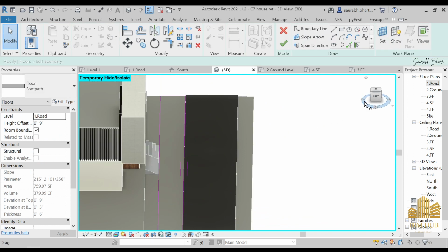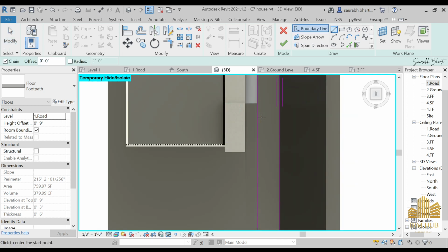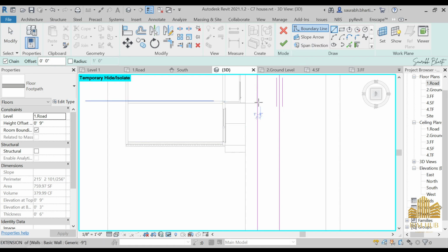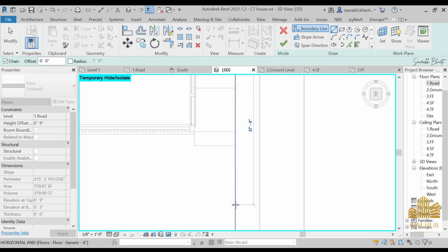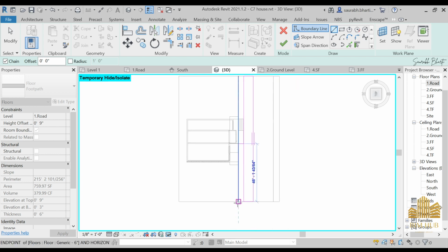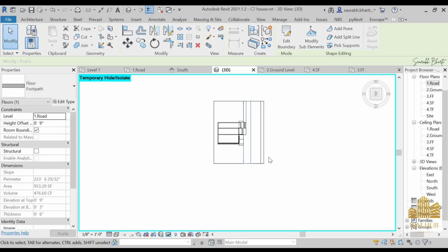There's a little bit more to be done, and go to Edit Type, consider making a line. Okay, first of all go to wireframe. Then consider this line from here till here. Trim it, this part done. Trim this part and this part, finish it.